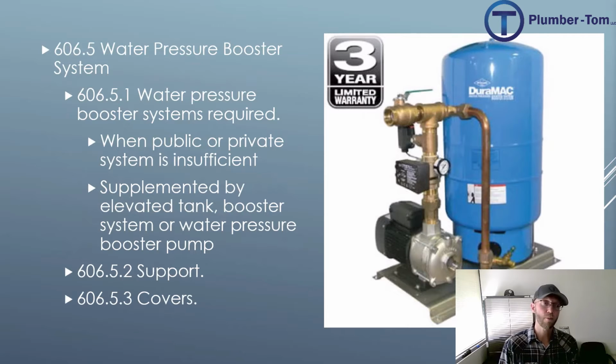606.5 gives us information about water pressure booster systems. This is where if you don't have enough water coming in, last presentation I mentioned, what if it's at 25 psi from the city? Well, then you can boost it up. You get a tank, you get a booster pump, and you push. That's what this is all about.